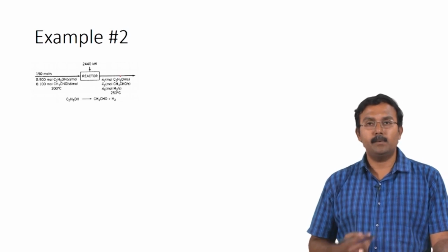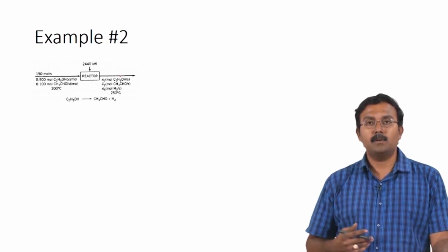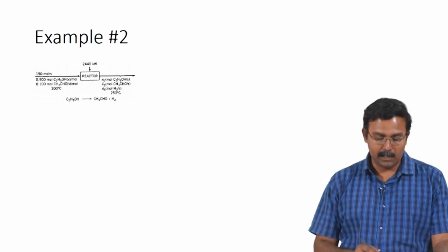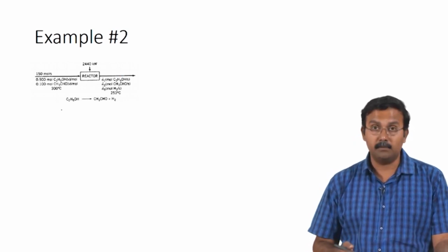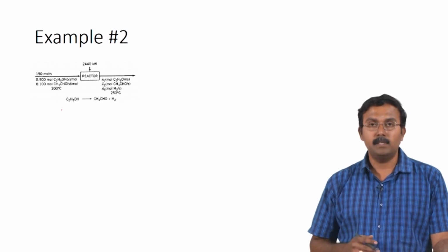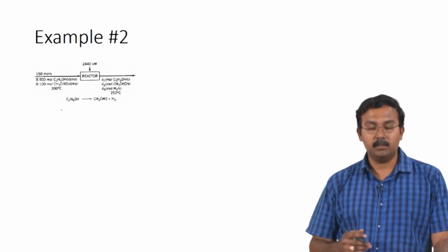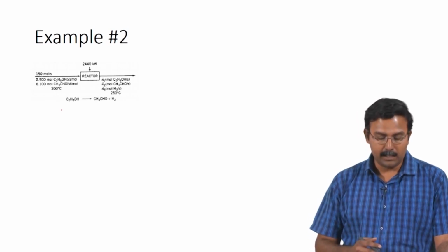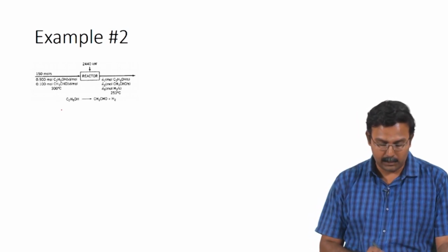How many independent equations can we write? If we were to write elemental balances, we would be able to write 3 equations, right. We can write a carbon, hydrogen and oxygen balance. However, what you would see is oxygen and carbon balances are dependent on each other. We can try writing the equations and see how that actually comes out.